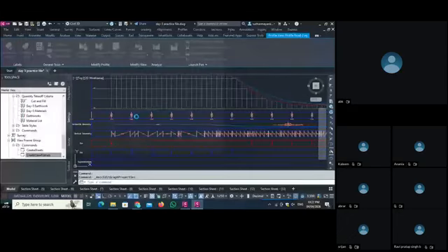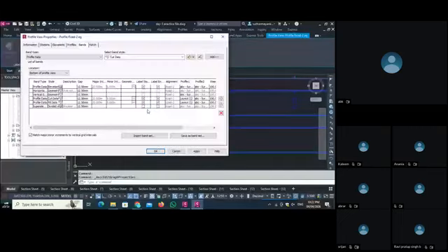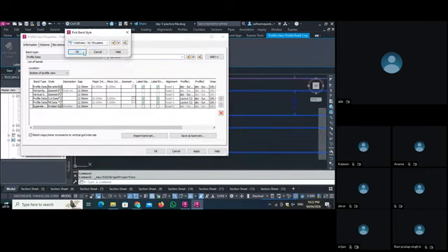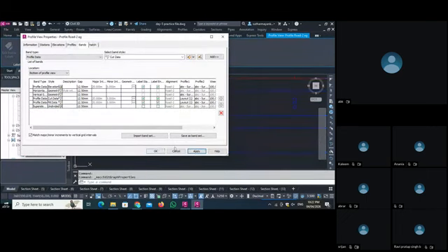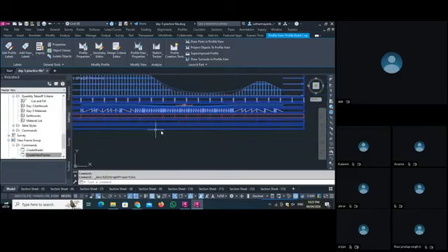So as you select the super elevation, the bar is there. Now to make this super elevation visible, if you select the wrong thing, then your super elevation will not be shown. So make sure that whatever crown you use, you have to select it properly. See, this also is not my crown. Okay, apply. Okay, so as you set your super elevation, it will show here.